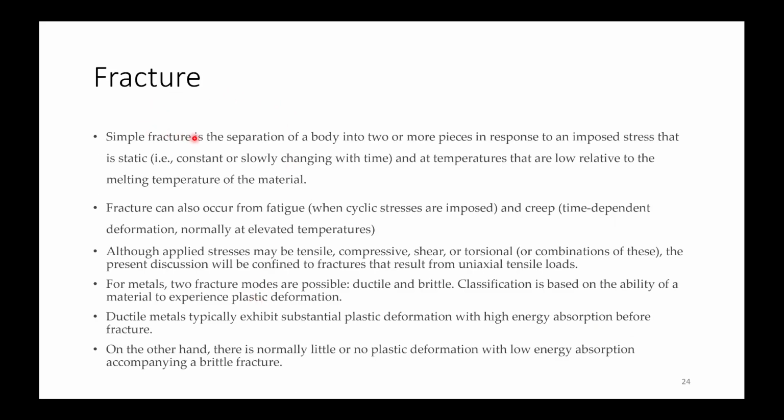Now simple fracture. Fracture can be defined as the separation of a body into two or more pieces in response to an imposed stress that is static. When we are studying fracture mechanics, we are assuming that this stress is static or very slow compared to what we see in case of fatigue loading, and at temperatures that are low relative to the melting temperature, so as to separate it from creep type of deformation.